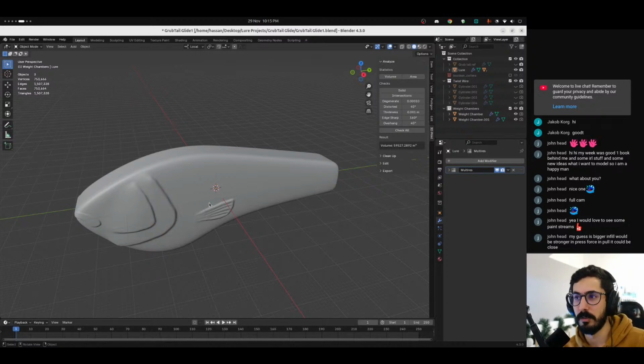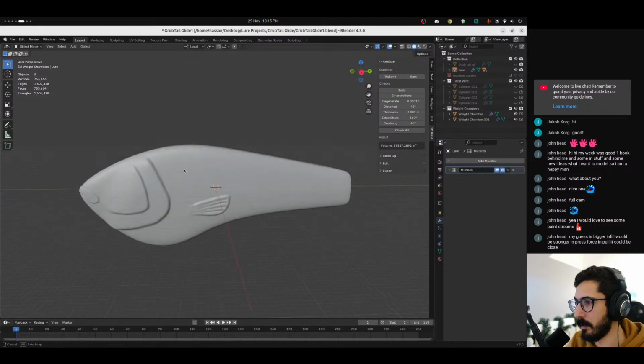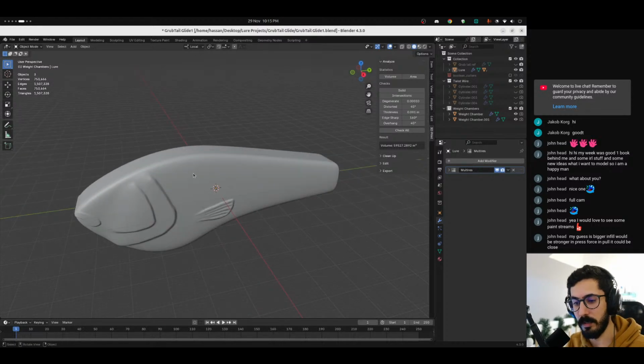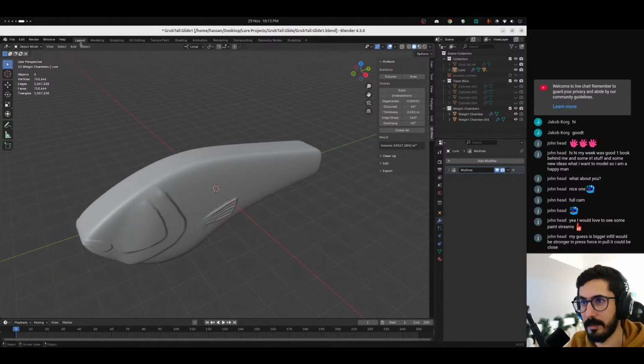And then 4 and over, it doesn't make a difference. But if you go from 1 to 2 to 3, there's a huge difference in strength. And then infill, it was also up to like 20%. From 20, the only way to get a lot stronger is 100%. Anything in between doesn't make any sense.